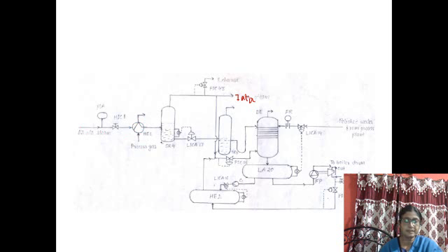That means the control loop is a pressure control loop along with the indicator facility, along with the controller. And if the pressure is less than 7 atm, that will be released to exhaust, and this 7 atm steam line is used here. Just see the path.